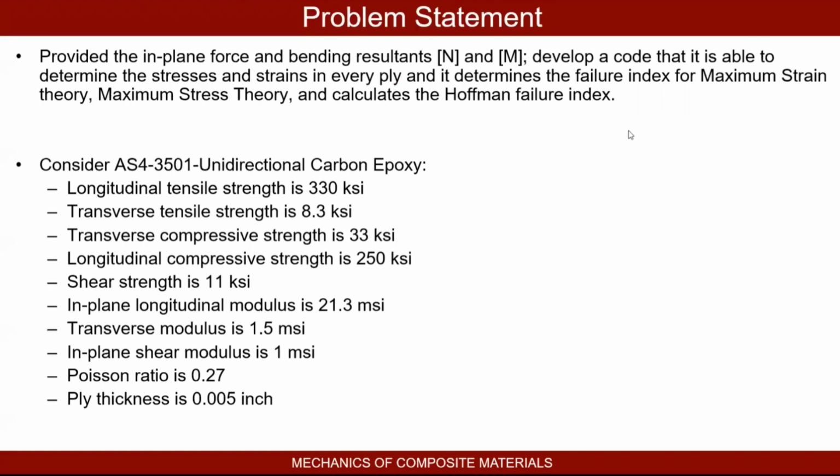So let's dive into the problem. We'll have a plate with a given layup that has force and moment resultants applied at the edges. So we are going to develop a code that is able to determine the ply-by-ply stresses and strains and evaluate those as compared to the allowables for the material to try to inform our design and predict failure.